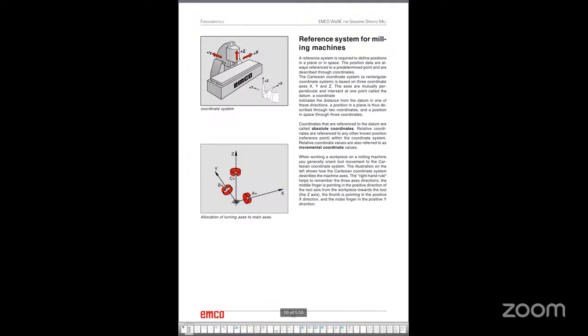Okay, so for example, if I type X0, Y0, the tool will be here because this is the origin, right? And then I give X80, Y50. So that means this X distance is 80 and Y is 50. Say this is point P. So the value of Y is 50, all the distance from this origin point 0, 0. So the tool will directly go to here based on this point.